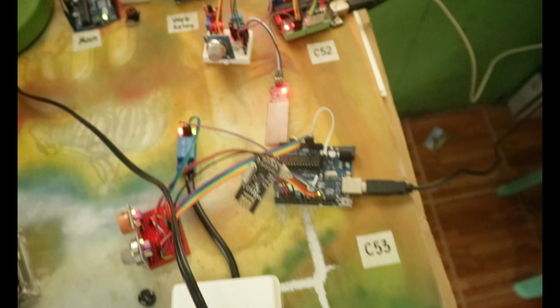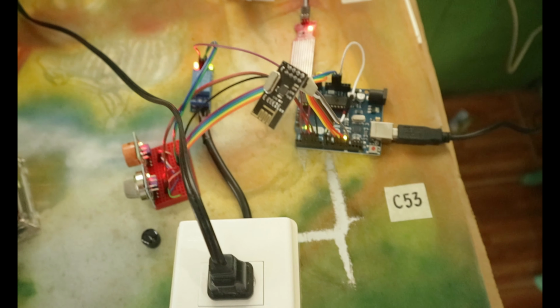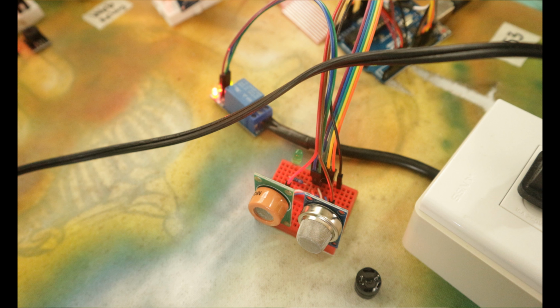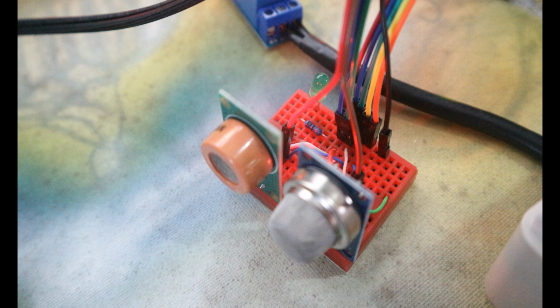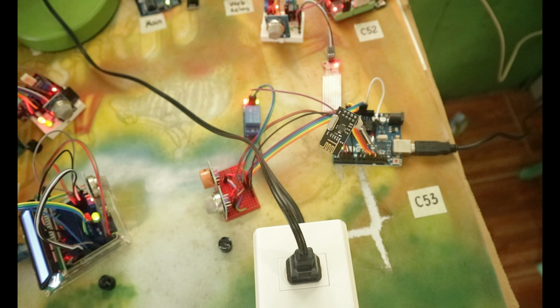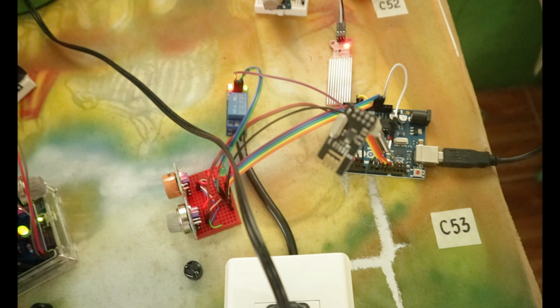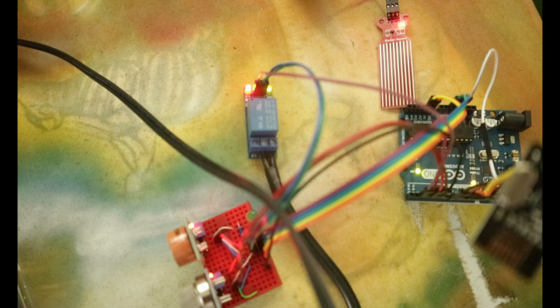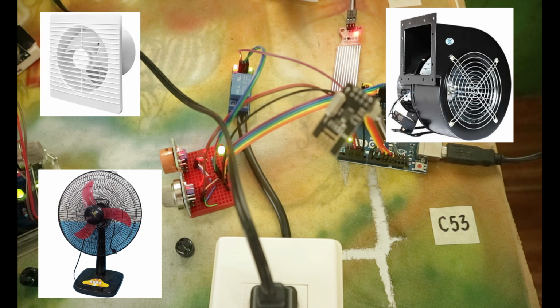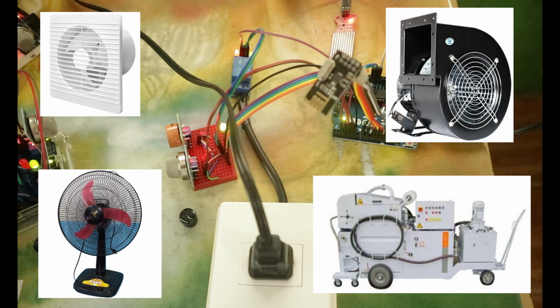Fifth, component 53. Also from the kitchen safety components is component 53. It is fitted with 2 gas sensors, MQ3 and MQ4, and a relay switch. The MQ3 gas sensor detects smoke, alcohol, and ethanol, while MQ4 gas sensor detects methane and combustible natural gases. To dissipate and disperse the detected gases, the relay switch can be used as conduit for home appliances and high voltage equipment to be added into the system. An example could be an exhaust fan that disperses the detected gases.